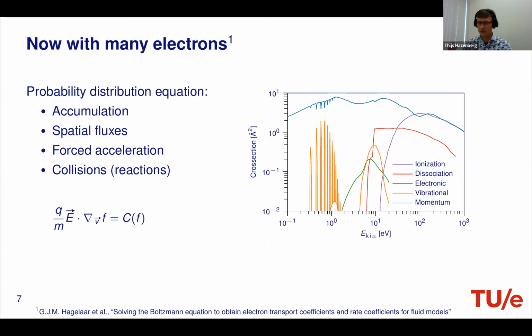So if you now imagine that distribution function, then you see that basically no, or a very, very small portion of the particles has enough energy to dissociate this molecule. Which means that at 1000 Kelvin, it's difficult to dissociate anything, which means that it is difficult to initiate combustion, which then leads to long ignition delays or slow flame speeds.